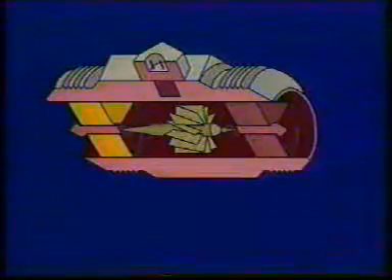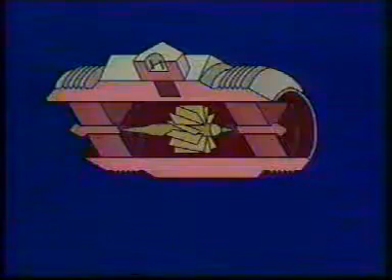Most turbine flow meters have straightening vanes upstream of the rotor to ensure the fluid enters the rotor free of swirls. Rotor designs vary from one model of axial turbine flow meter to another, but the rotor generally has a hub from which the flow vanes project. The hub rotates on sealed bearings. Whether the rotor is linked to a counter that counts its rotations or is connected to an electrical device, the actual flow rate is determined from the number of rotations of the rotor per unit of time.